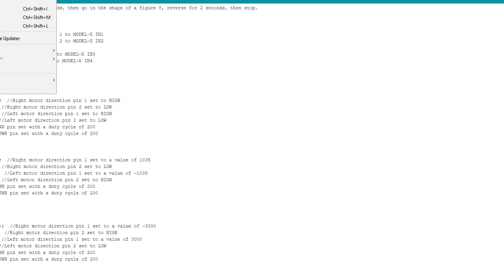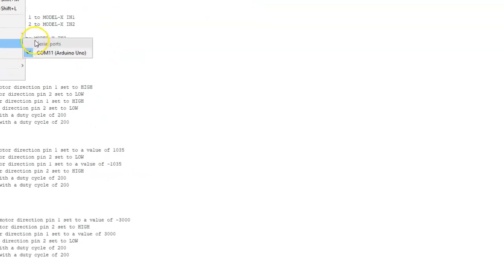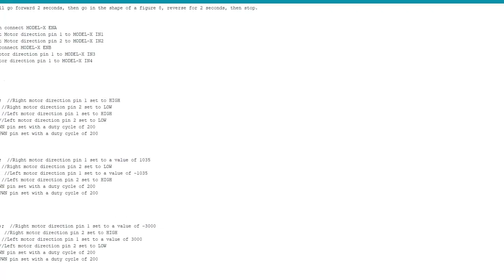The final thing you need to know is that there is a communication port your computer uses to communicate with the Arduino, and it needs to be on communication port 3 or higher. If you go to Port, it shows the serial ports, and we click 11. It's on port 11. You will see down here as well that it says communication port 11. Pretty hard to see, but it does. Okay, so this is your Arduino hardware.